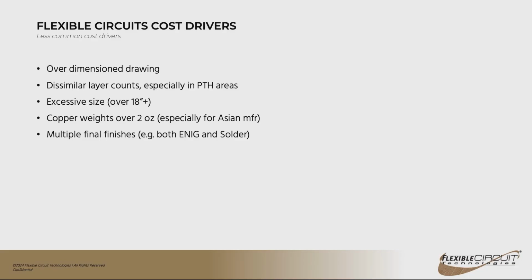Crosshatch shields are used on a regular basis for high-speed signals, and it gives you two benefits. The first benefit is that you're removing some of the copper in that plane, which is going to make it more flexible. The second thing is that by removing the total surface area that is in broadside coupled to that plane, you are reducing the capacitance, and therefore you can actually make your space in between those layers less.